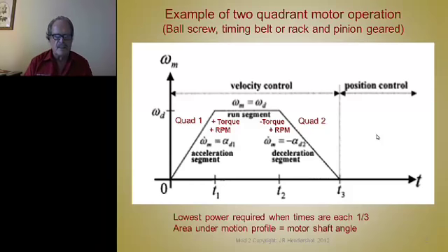Now let's look at this picture here. This is a very important picture for motion control. And a lot of these electronically controlled motors are used for applications like this. This concept is applicable to accurate angular positioning of a shaft with big inertia loads or low inertia loads. This picture is applicable to all linear motion applications. So it's been proven long ago that the most efficient positional move is accomplished if the shape of this velocity profile is in the shape of a parabola.